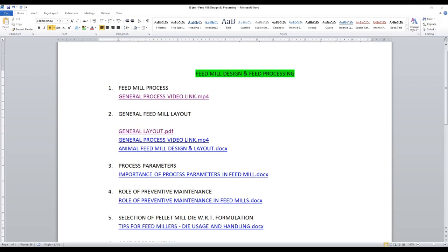Finished goods stacking heights will not go up to 18 feet, due to dust formation, the PDI, the bags, and ease in handling. Generally, feed millers do the stacking at 10 or 12 feet maximum. And raw material we can stack as per the labor and the area. In some areas, labor do the stacking up to 18 feet. In some areas they go only to 15 feet.